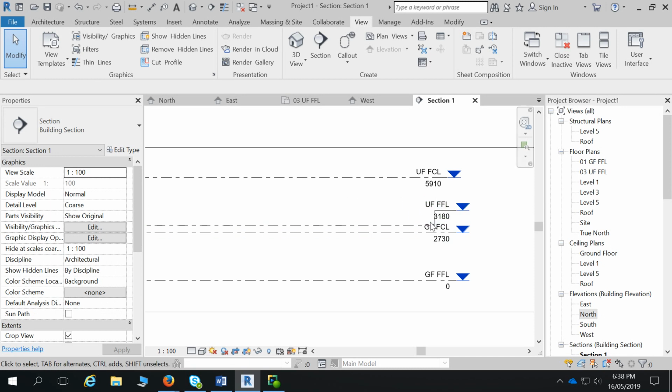See how that section marker there's got the upper floor level zigzagged as well. Was everyone able to find that elbow zigzag line and do it? It can be a bit hard to find sometimes. It's one of those ones that you've got to know that's there. So you select the level. Copy it says. And then you can apply it to it if you zigzagged it. So you can do it north to south and east to west. You just can't do it to 1 and apply it to all 3.